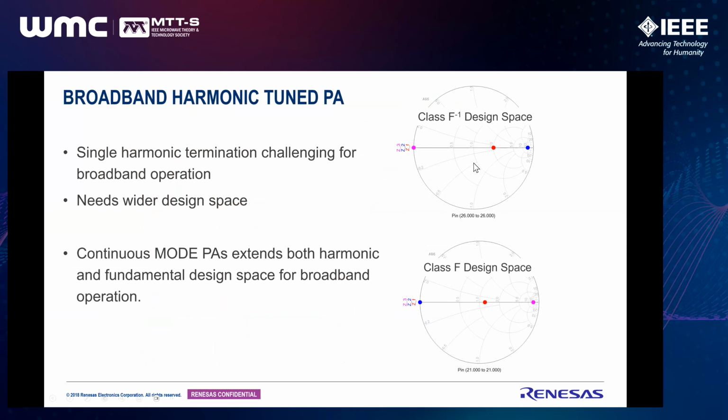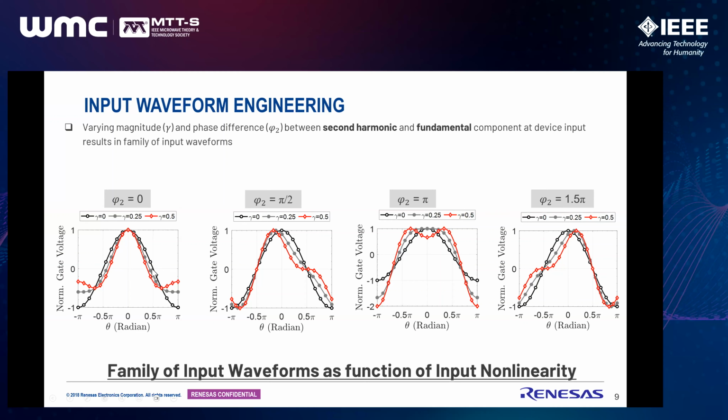As you can see, the waveforms are shaping in different types. One quick observation, you can see that sometimes waveforms are getting contracted, meaning when your gate voltage is getting narrower, when it is translated into the drain current, definitely your conduction angle is going to be changed. On the other hand, from the nominal black one, in this example the waveforms are getting extended.